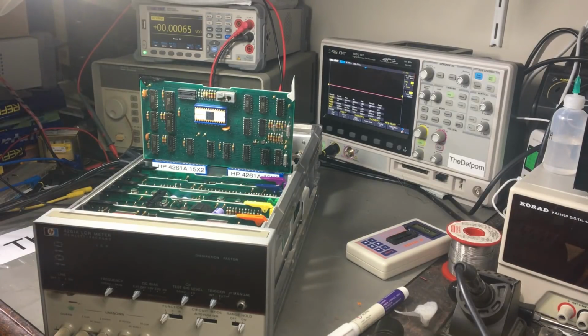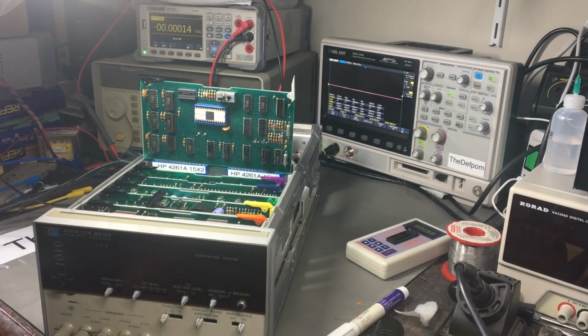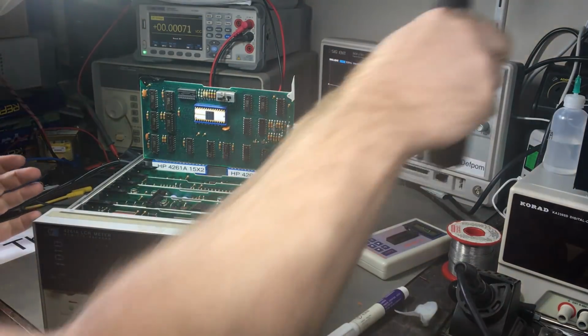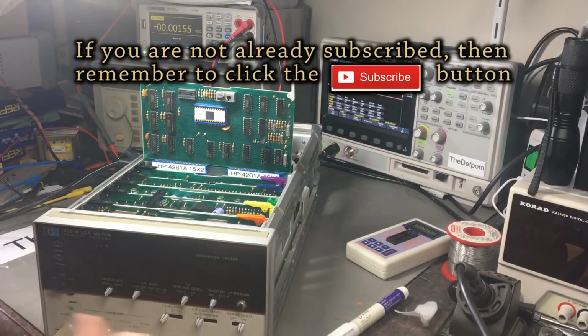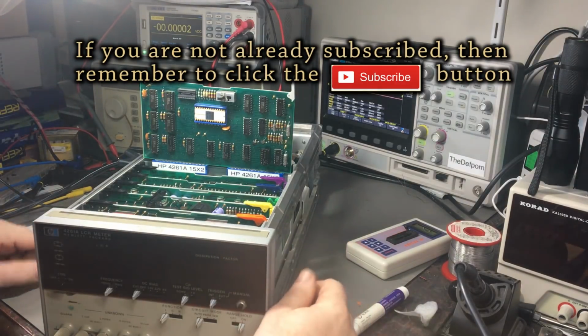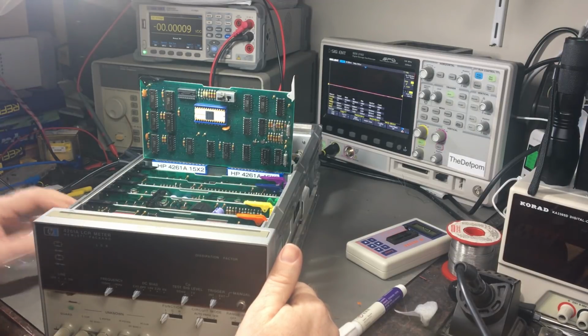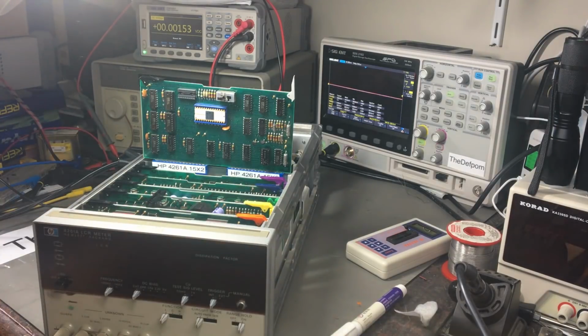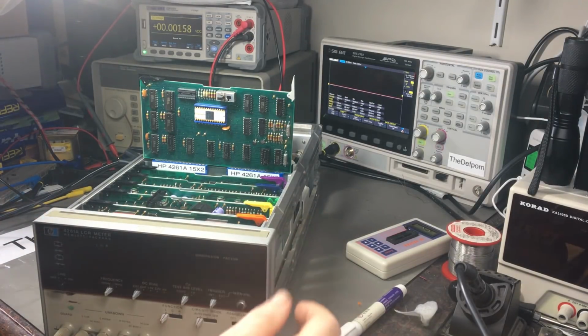Right, so it's now time for the next part. If I carry on, assuming that this signal here is okay, and assume there's a documentation difference between what's actually there and what I'm seeing, or that what I'm seeing is close enough to the documentation to be correct, I'll just carry on. Since I'm unsure about that, I've made a note to say something's a bit weird here, and I'll move on. The next step is to make sure I've got trigger internal,